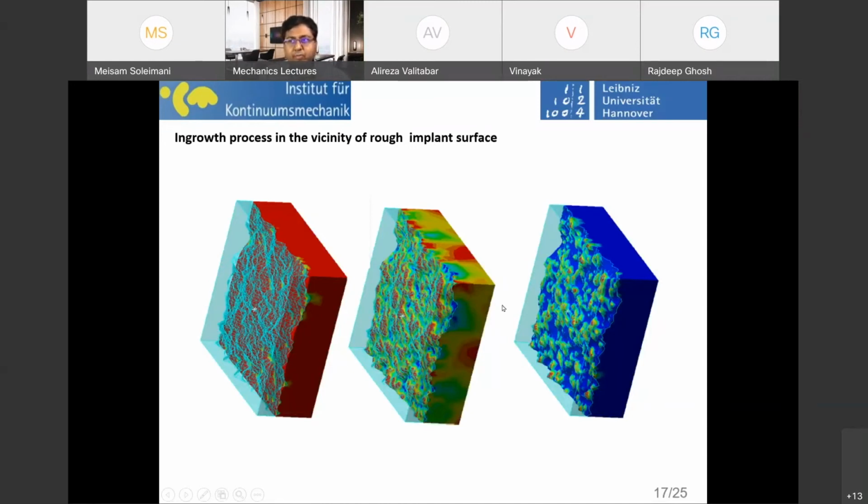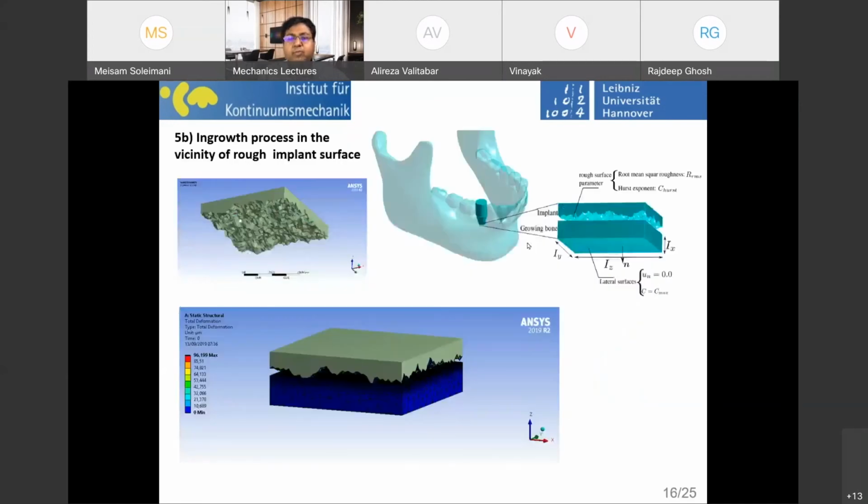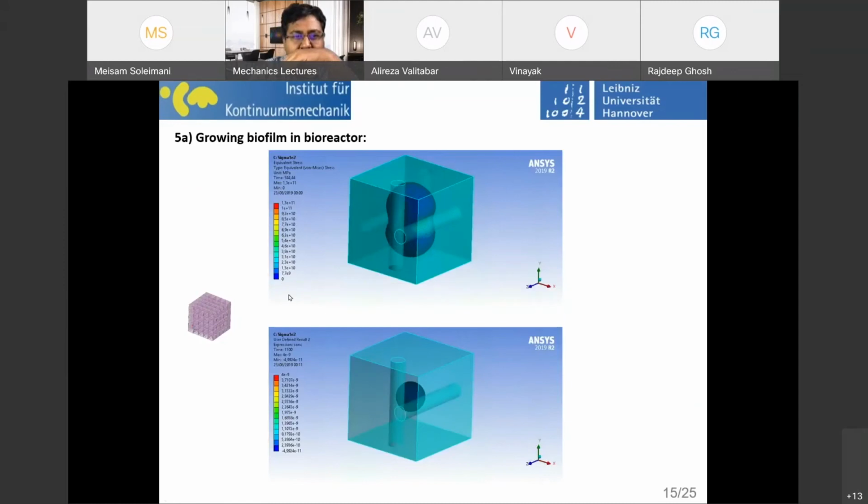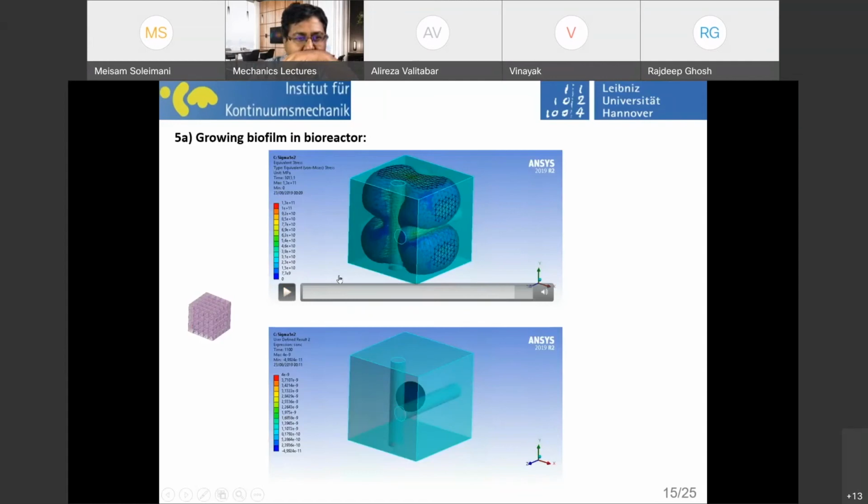In a buckling problem, what happens is that you are facing a bifurcation in the solution procedure, so you need to enhance your solution procedure in order to keep the problem stable. In particular, this problem was very horrible because the material came into contact several times, and it's very, very difficult to get convergence. Even here we have a self-contact.